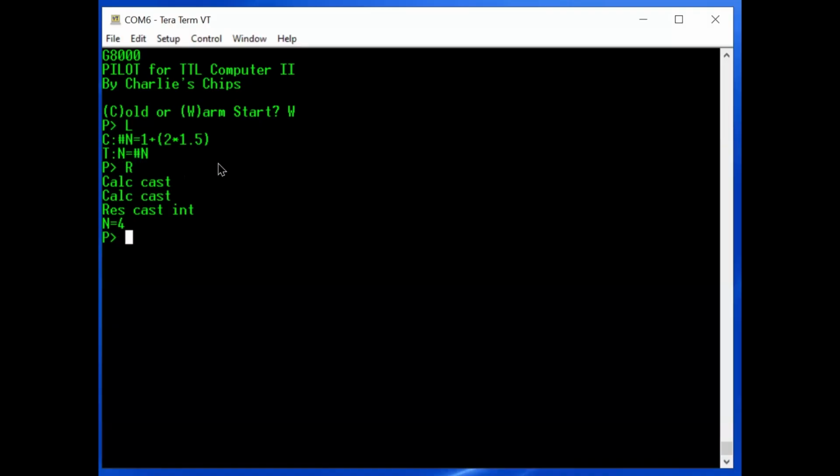So that's just to show you there's a lot of complications going on with the fixed point numbers and the integer representations. Pilot is doing all of this right for us behind the scenes, handling all of the type conversions automatically. We just type a simple algebraic expression, and Pilot takes care of doing all of the type conversions that are necessary for our result to be correct.